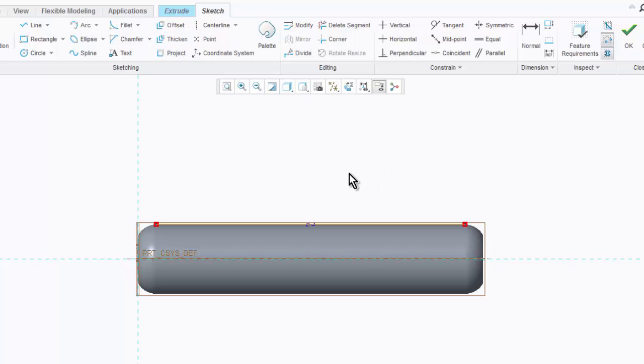So we'll select single and close, and we're going to make an arc. It's going to be a 3-point arc, end, end, middle, and we're going to delete the segments of the projected line.